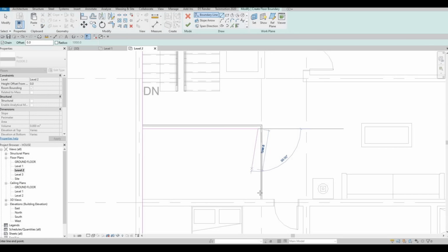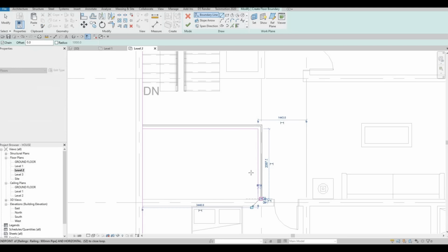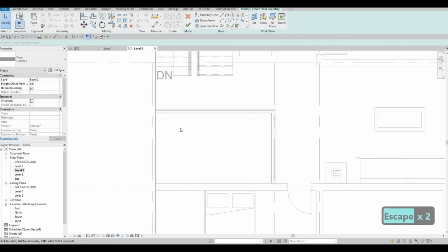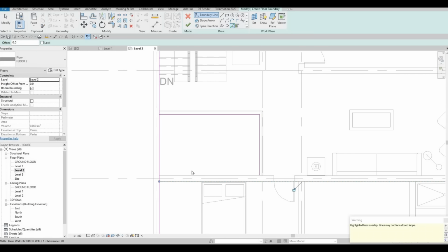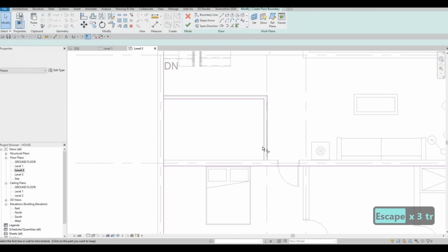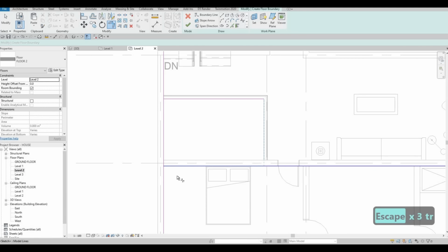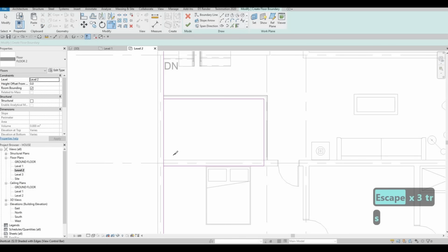Of course, there should be a gap between the railing and here. And then now, what I'm gonna do is I'm going to pick this line actually, and then let's trim and extend here, and then SL here to slice it up, and then trim and extend right here as well.